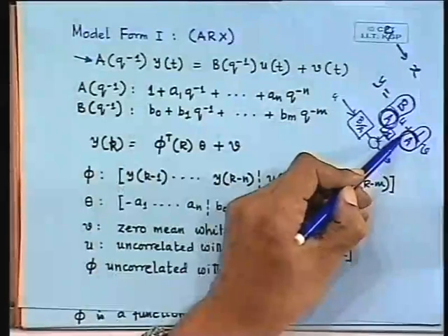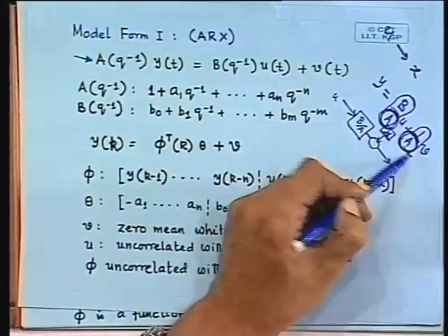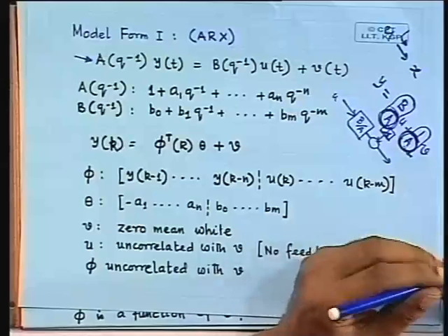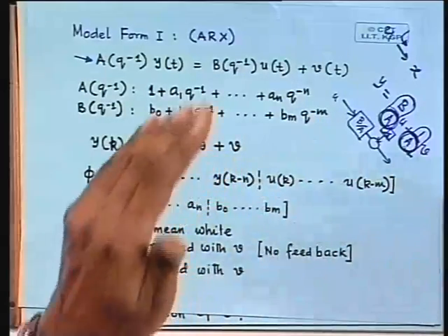So that means the A polynomial, which is the determinant of sI minus A, or in this case zI minus A, is coming in the denominator. So this noise must have, just like u to x, that pole 1 by A. Now v is also having this 1 by A. That means v must have entered along with u. So you are kind of assuming that noise is also being processed by the system.